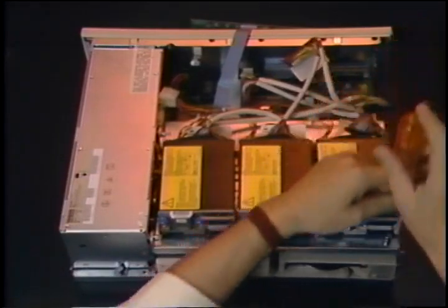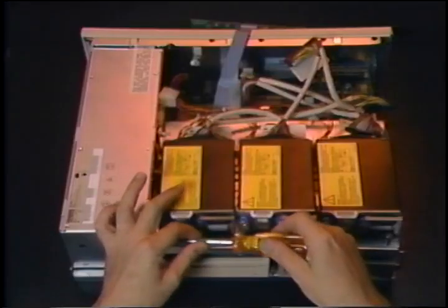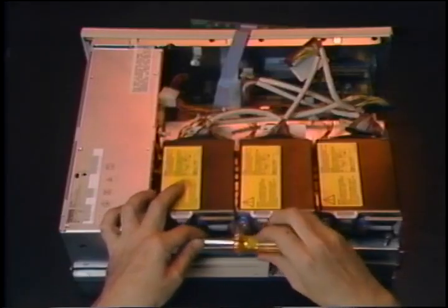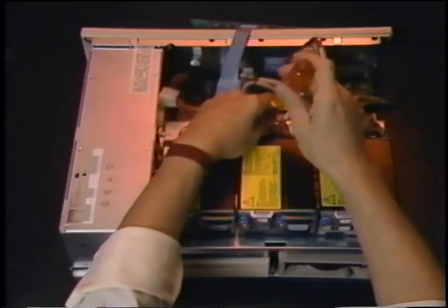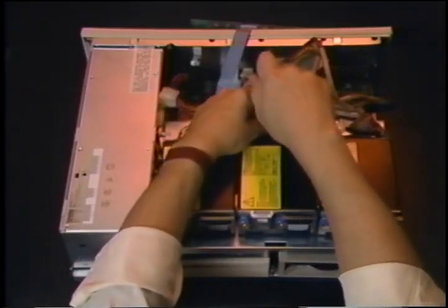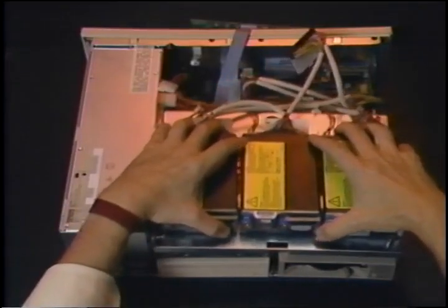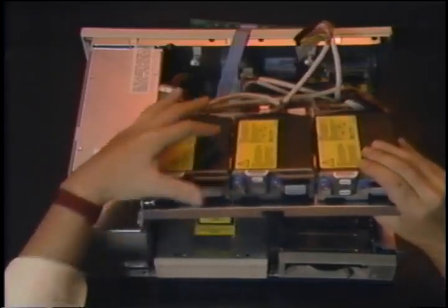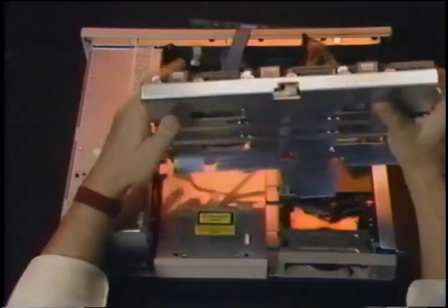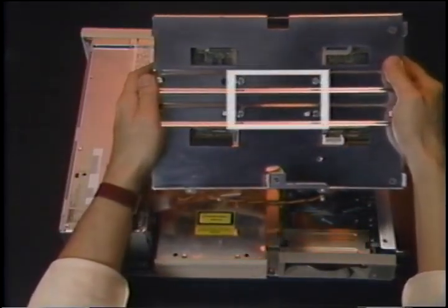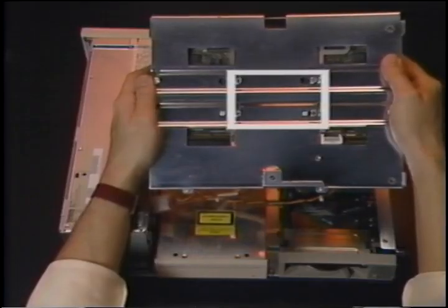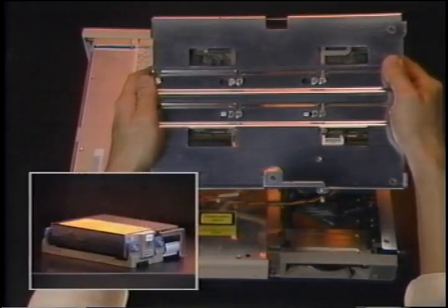The top drive panel is secured with 5 captive screws, including 1 in the access hole. Loosen these and remove the entire drive assembly. To replace any drive, remove 4 screws from under the drive. For any RZ, try to preserve the user's data. Always replace and test the controller before replacing the hard disk assembly.